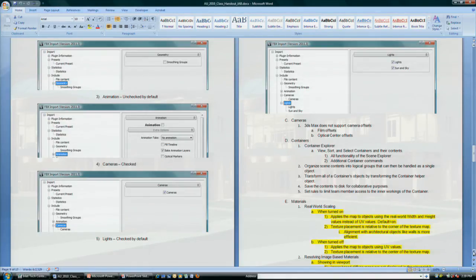I will bring in some lamps and light fixtures that are put in by the architects, but mainly I like to stick to the MEP engineer's lighting. When I bring those lights in, initially I will put them on their own layer coming out of the MEP model when I do the transport. But eventually, I like putting all that, the sun and the sky and the lights, on layer 0, so I know exactly where they're at, so I can very easily go get all those.